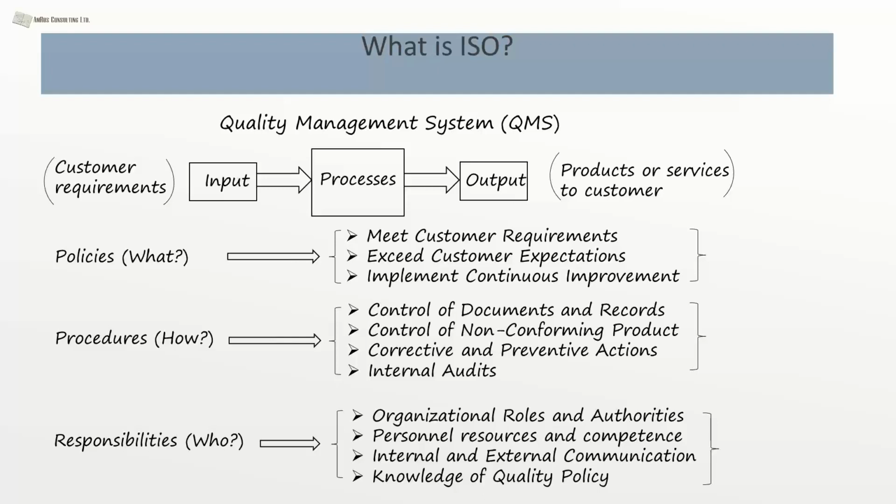So the other thing, which is very important in improving the quality, is to look at non-conforming products. Non-conforming products could be evaluated as part of your manufacturing, and when you detect or observe that you have some non-conformances, then you immediately take action to do the root cause analysis. What is wrong, what caused this non-conformance, and then come up with a solution.